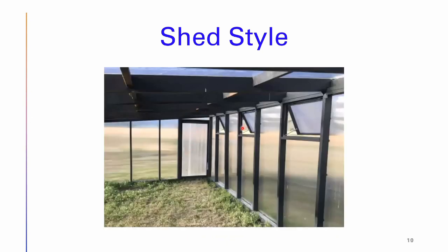This is another shed style. I've built several shed styles for people. This is one example. This just shows a 1.5 to 12 pitch roof. The glazing is a smooth surface. I think it's the IBC, ASCE 7-10. That's the structural engineering code, I guess you'd call it. And it defines something called a smooth surface.